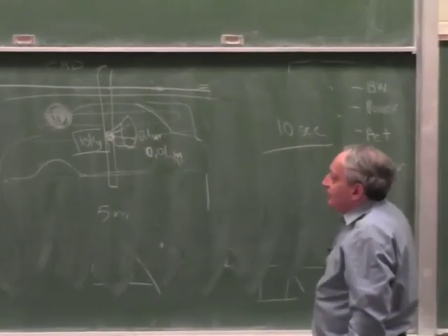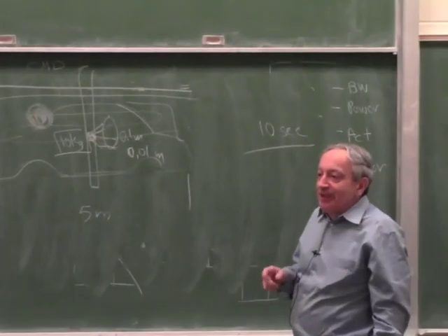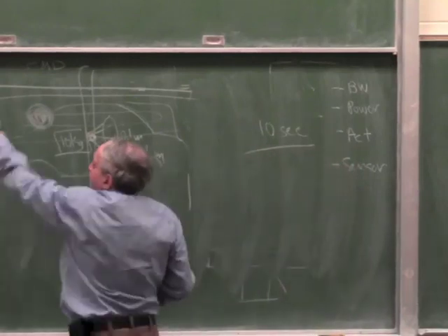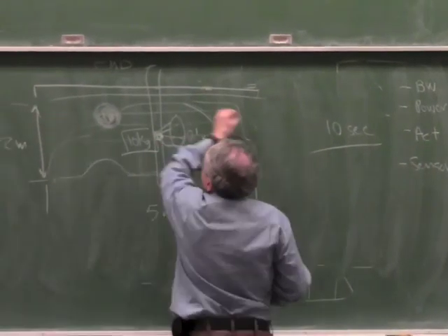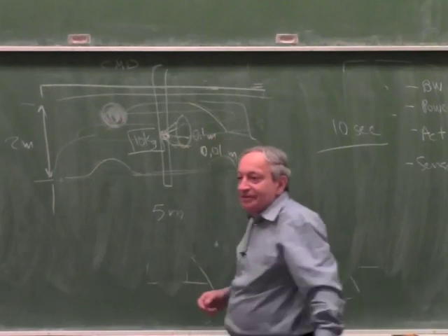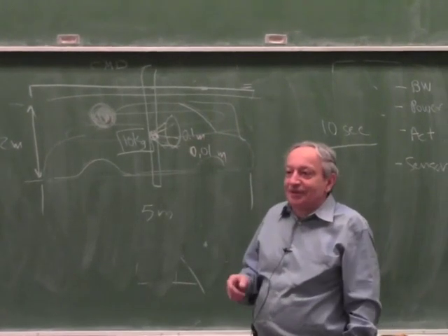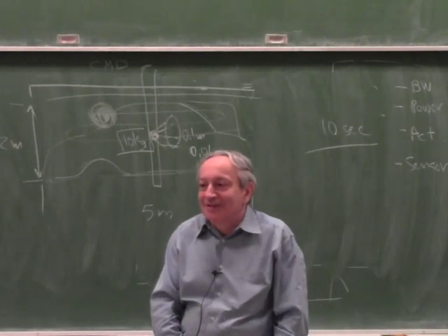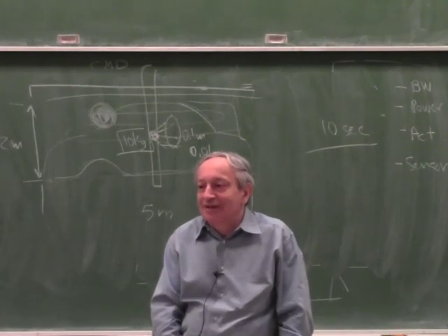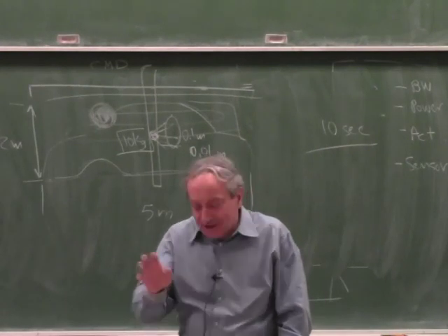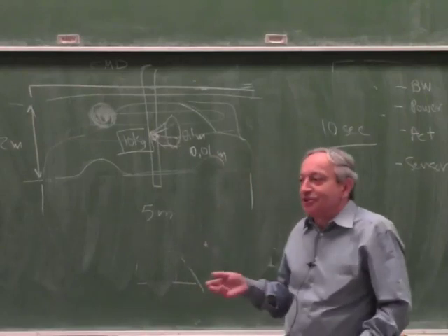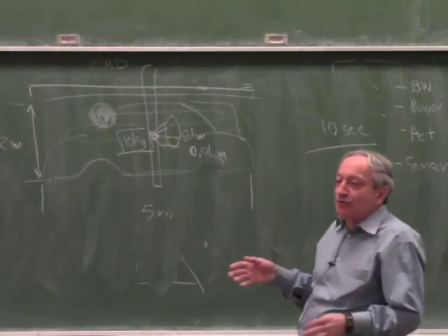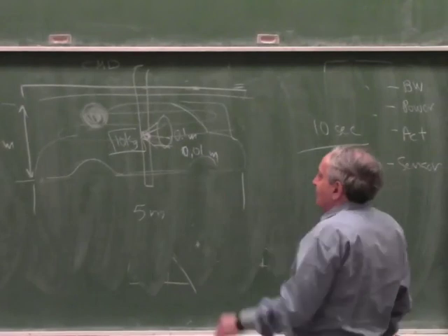So let's start with a simpler question. Is it better to do the raster this way, or is it better to do the raster this way? What do you think? I think going over. Yeah, why? Fewer direction changes. Exactly, because with direction changes you sometimes lose accuracy, so for sure it's better to do the raster in the long direction.